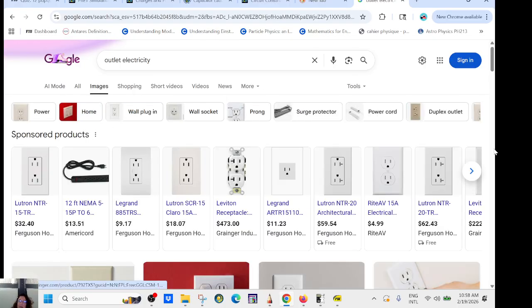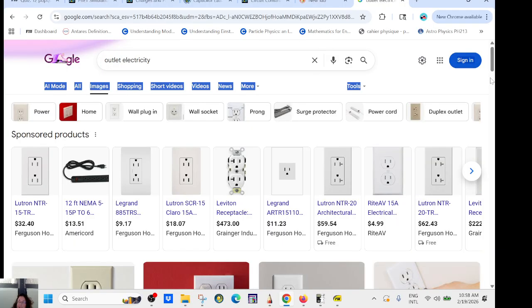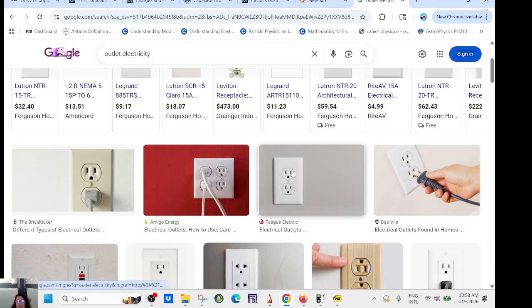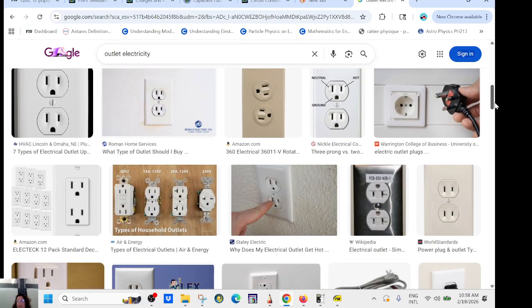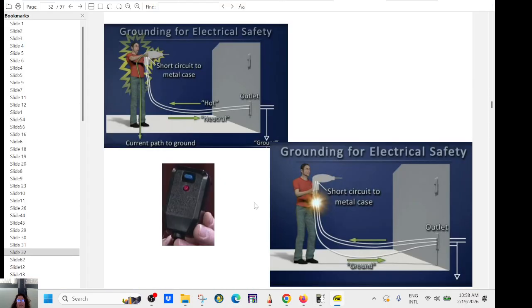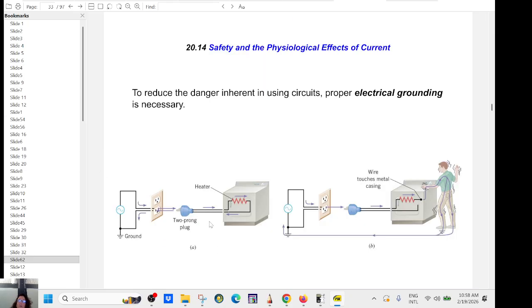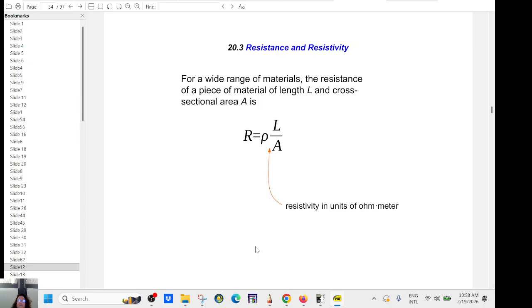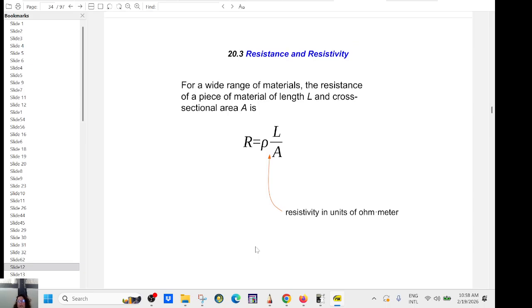Okay, so here you have the hot wire. The return path here is connected at some point to the ground, but maybe not that safe because you still have some voltage drop to go through. This is connected to the ground, so if you stick something inside there, you touch it, you're going to be safe because it's connected to the ground. Used to be, there was no connection to the ground, right? They were not very good at safety. Okay, so not good because if there is a leakage somewhere, boom, you are the return path. Are we good?